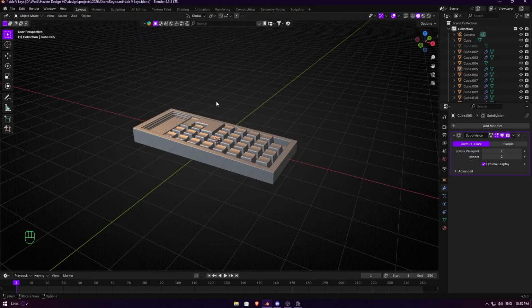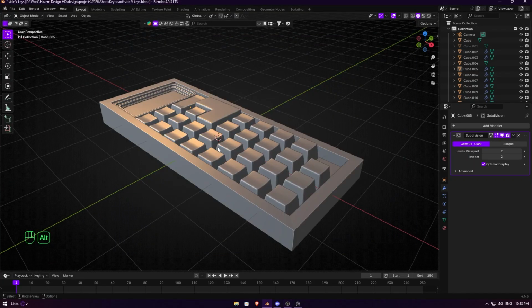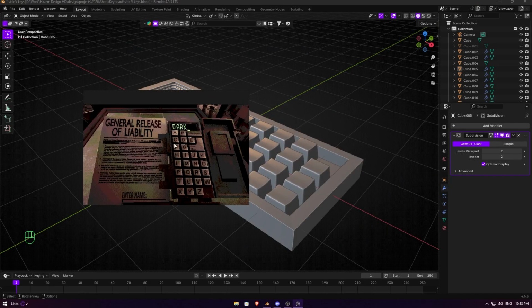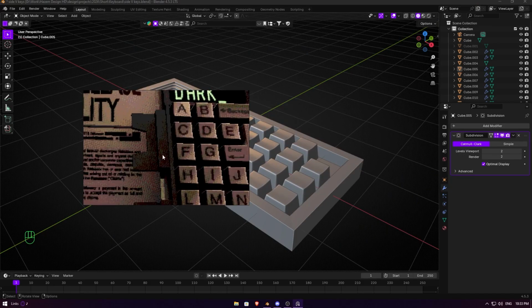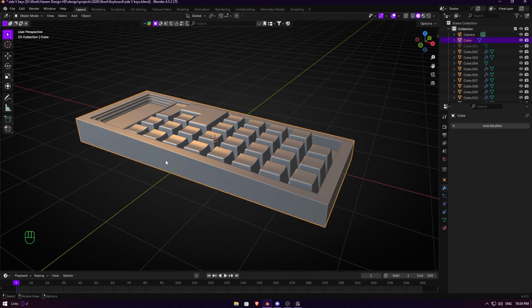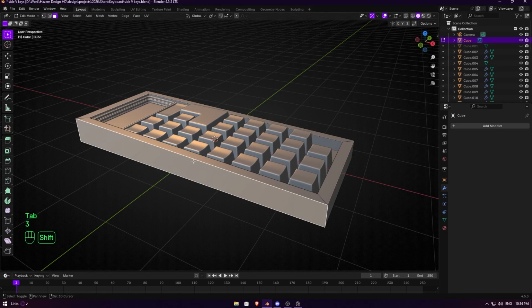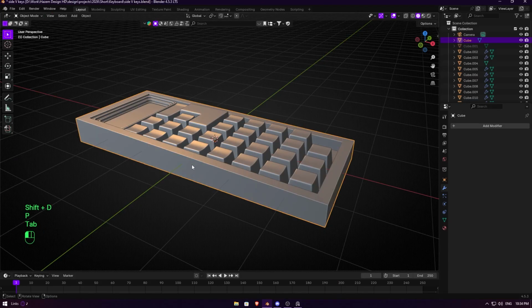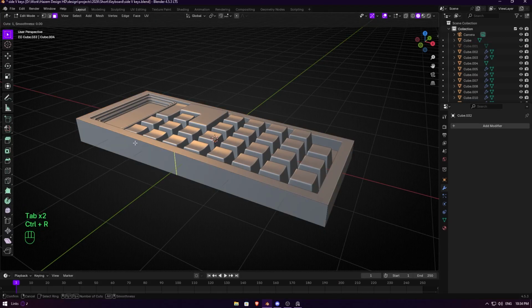To complete this project, I think I'm gonna go here and check on reference. So here it's simply like a cube and another extrude here, like insert face, and it's going here with this cut. So it's pretty simple. So if we go here, I'm gonna go with this side and Shift D and then B to separate it. Then go select it and try to assign a loop cut here, like this, and another one here, and Ctrl B for the bevel.